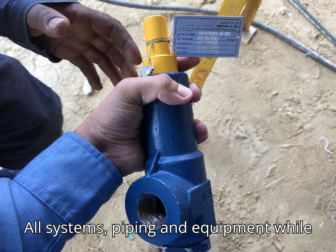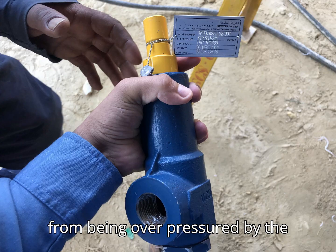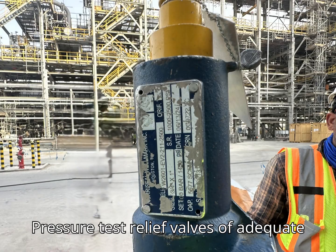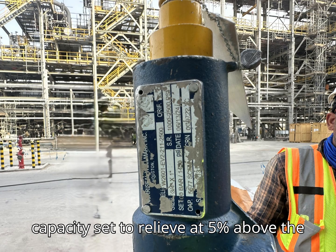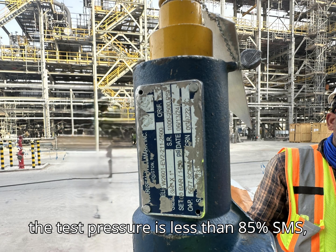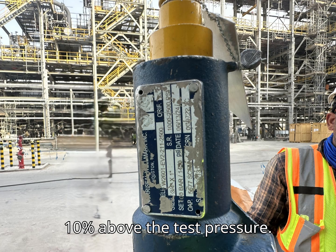Point 5.7, SAES-A-004, protection from overpressure. All systems, piping and equipment, while being pressure tested, shall be protected from being overpressured by the following. Pressure test relief valves of adequate capacity, set to relieve at 5% above the test pressure, shall be installed, unless the test pressure is less than 85% SMYS, in which case it can be set at 10% above the test pressure.